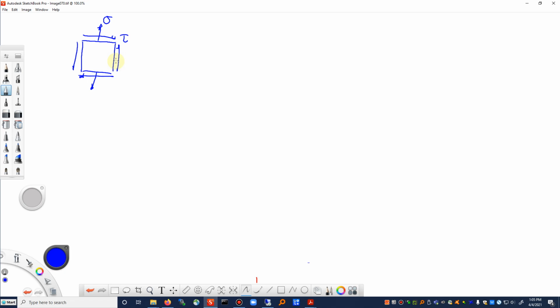There's another type of testing machine that's a little bit more rare, but it does exist. There is one in which you can apply biaxial loading. So you can apply a force in the vertical and a force in the horizontal direction on a specimen, and then you can get fatigue that way. It's a little bit more common in composite materials, but it can also be used in metals as well. Let's take a look at tension and torsion. We'll just keep it as two components of stress for right now.